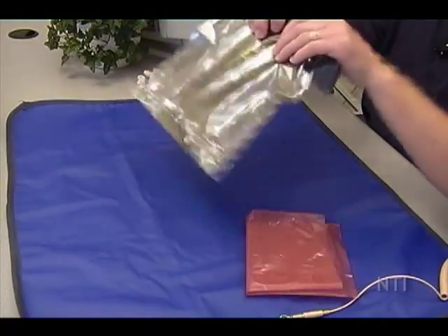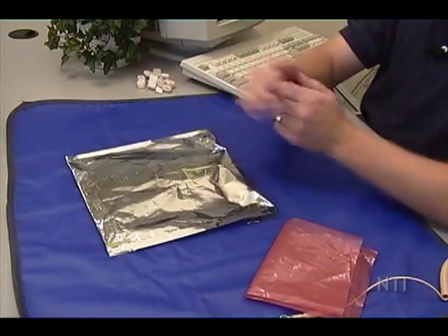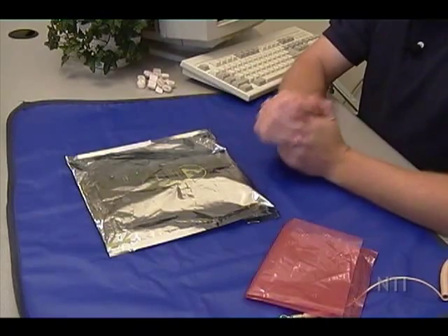To protect your components, all you have to do is slide them inside the bag, fold it over, apply a little adhesive, and that component is now safe from electrostatic discharge. This is really important, especially if you're going to be transporting it somewhere. Say you put it in a box and you drive around and you pull it out of this box and you hand it to somebody. The chances of a discharge are really, really high. So I strongly recommend you use these, especially when you're transporting it or sending something through the mail.